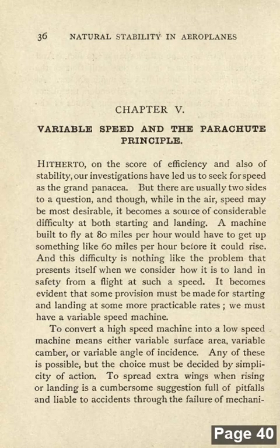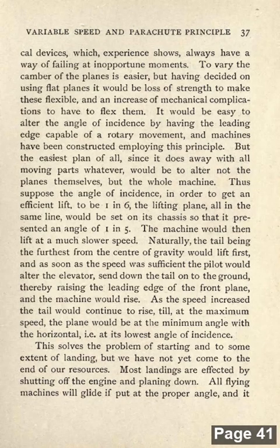To convert a high-speed machine into a low-speed machine means either variable surface area, variable camber, or variable angle of incidence. Any of these is possible, but the choice must be decided by simplicity of action. To spread extra wings when rising or landing is a cumbersome suggestion full of pitfalls, and liable to accidents through failure of mechanics. Such devices, experience shows, always have a way of failing at opportune moments. To vary the camber of the planes, having decided on using flat planes, would be loss of strength to make these flexible and an increase of mechanical complications to have to flex them.